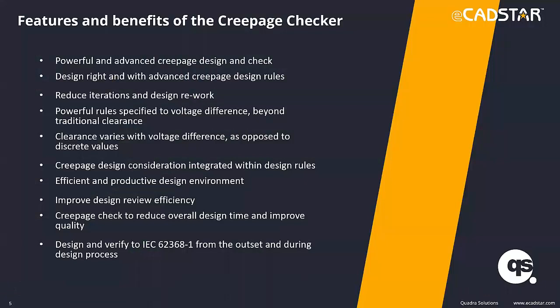So just a general overview then, just to highlight some of those features and benefits. It's obviously a powerful advanced creepage design and check. We can design right, and with advanced creepage design rules, we're reducing the iterations and design rework. It's a powerful rule specified to voltage difference beyond traditional clearance. Clearance varies with voltage difference as opposed to discrete values.